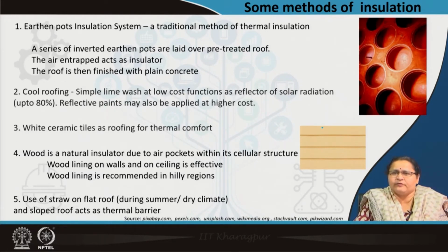Then even on top of it you can have straw placed. So, during summer you get a very comfortable interior. So, these sloped roofs are treated with straw on top of maybe a bamboo framework or maybe on top of clay to have thermal comfort.